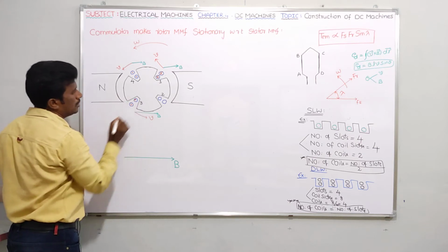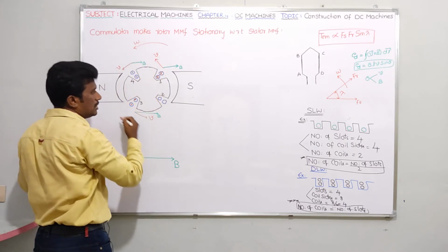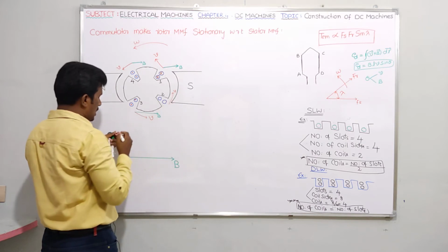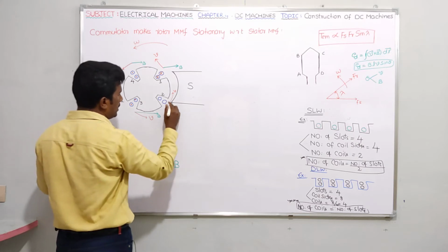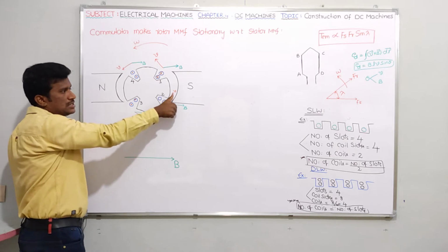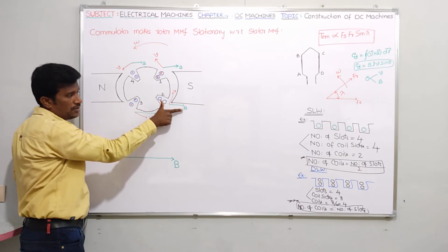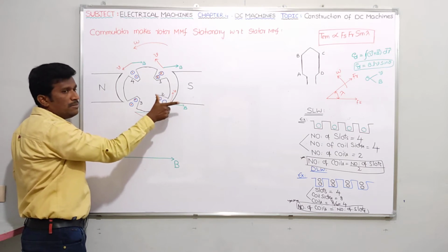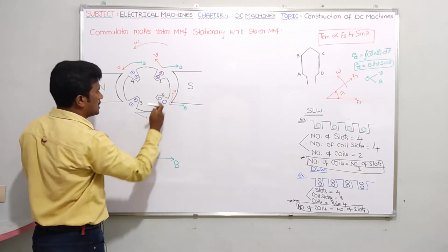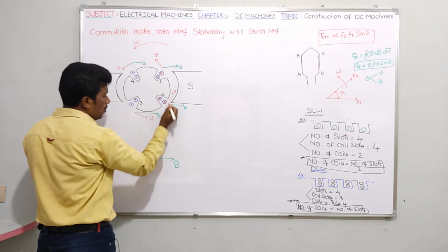Now similarly, tell me at slot number 2, guys. Slot number 2. So once again, for anti-clockwise direction at slot number 2, this will be the direction of linear velocity. And already you know direction of flux density means from left to right like this. So tell me, when a moving conductor, this thumb indicates this red color, direction of motion of the conductor, cuts the magnetic field, the direction of this flux density or direction of green color, EMF or current is induced in that conductor. Once again into the board. Into the board means what? Cross. Okay, cross. So guys, for deciding this direction of current only, we have taken all those things.